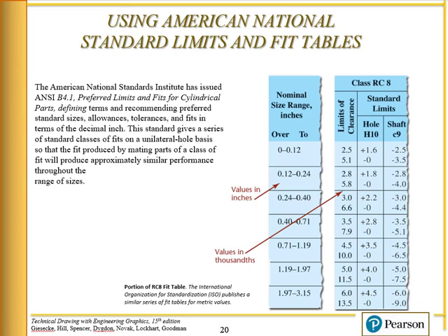So I provided the charts. They're in your material folder for the ANSI B4.1. They're in your charts. And then there's an example problem for lesson 3. You want to review that example problem. I'll put a movie in there too to walk through the example problem, but that'll tell you how to use these tables. So essentially what happens here is there's these classes of fits that are defined, and by using the tables you can determine the class of fits, and we'll talk about that a little bit more when I can show you the tables.